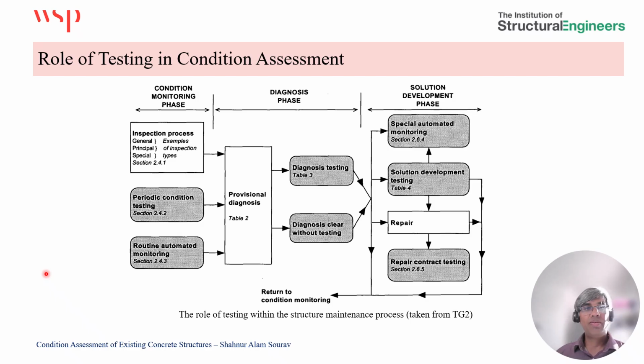Before I conclude, I would like to conclude with this slide. This slide shows the role of testing within the structure's maintenance process to ensure safe and durable existing concrete structures. The maintenance of existing structures can be divided into three phases: condition monitoring phase, diagnosis phase, and solution development phase. And in each phase, testing and monitoring has its role to play.